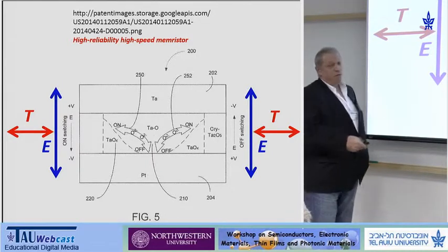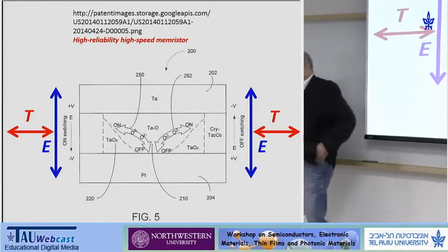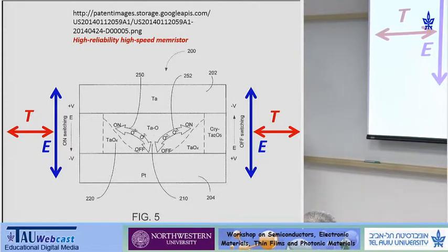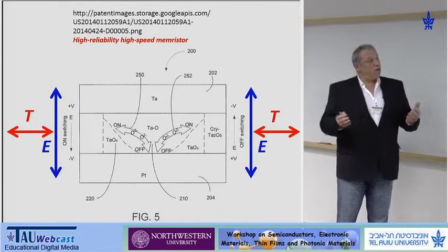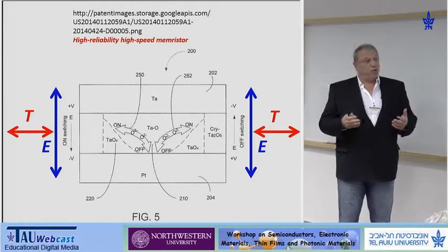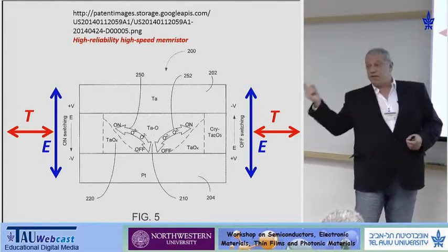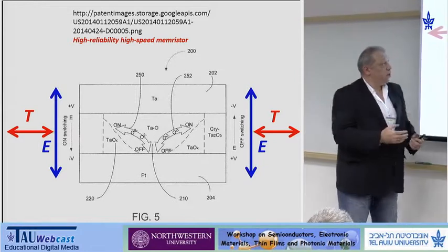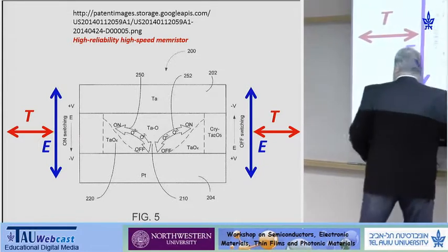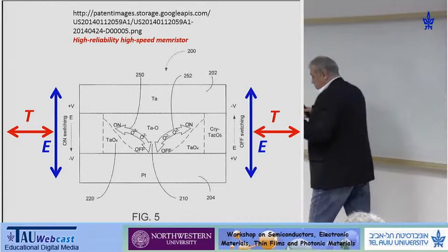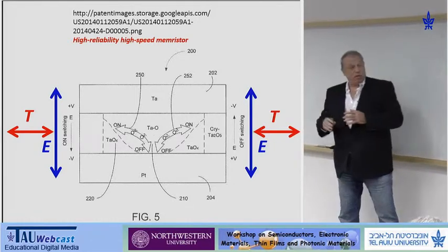At the same time, if you remember that crystallite, that means that very high temperature was reached there during switching. So there is a thermal field as well, which is called the Soret effect, or thermophoresis. Thermophoresis works annularly, so the atoms or ions, basically the vacancies, diffuse towards the higher temperature region.